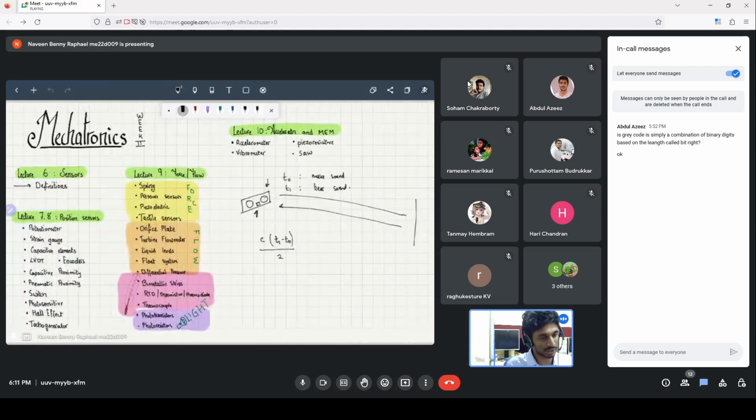The ultrasonic sensor is not able to figure out where the body will be. Similarly, if the wall is just too far away, the ultrasonic sensor won't get a rebound back, and therefore the ultrasonic sensor will not give the right value.